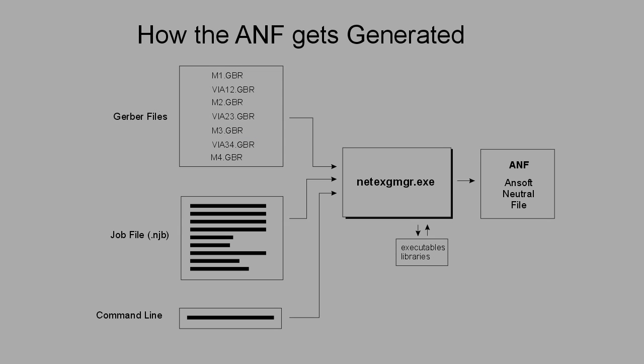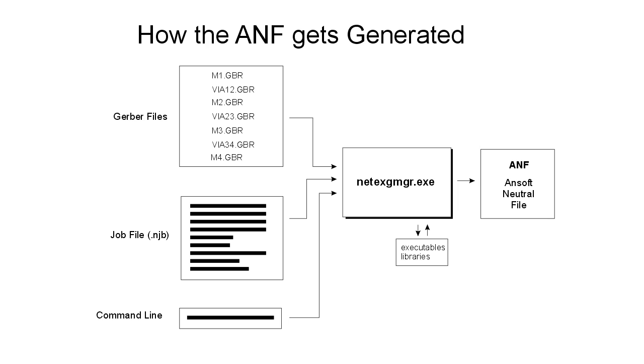So here's a little more detail about how this is going to work. NETEX-G Manager is actually a wrapper or manager that handles a number of executables and libraries that do the various steps required to go from the Gerbers into the ANF. So you call that on the command line pointing to the job file, and the job file points to the Gerber files, and NETEX-G Manager will then control the processing, and finally it'll output an ANF file and it'll be done. The user won't see any of that because it'll run in the background.